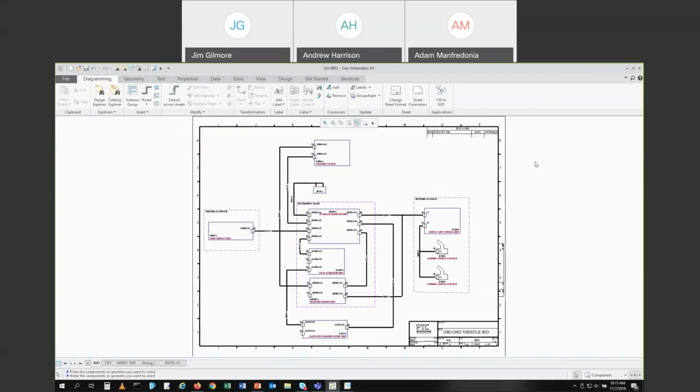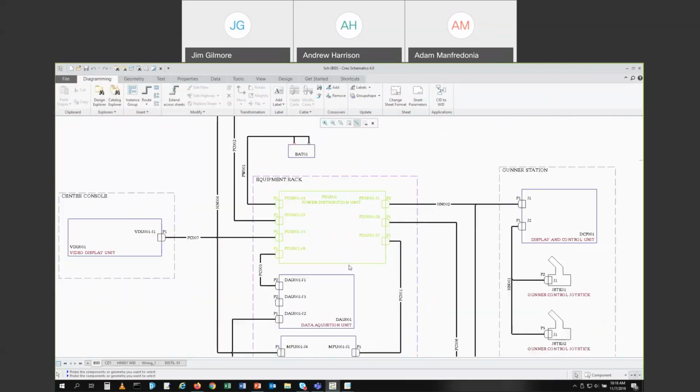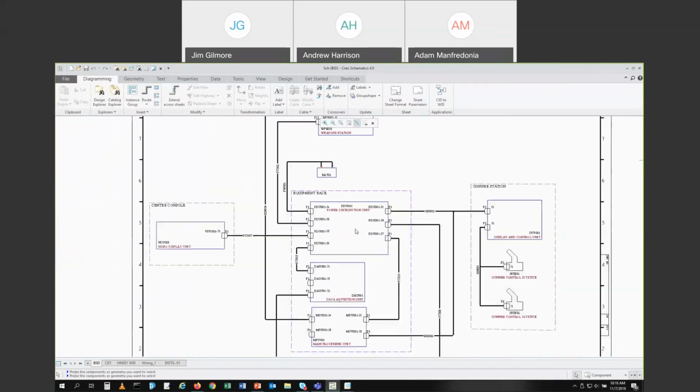So I'm going to start with the schematic piece of it and then kind of move through each of the individual components inside this. So if I'm starting out and I have electrical engineers who are doing my wiring diagrams for me, they may work in multiple different types of diagrams. They may start out in a concept design and do a block interface diagram where it has just the units themselves, it has their basic connections between them, and it knows that I've got 6 different units or electrical boxes of some type, and I know I have a connection from here to there or from here to there.